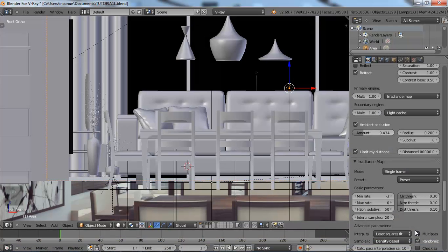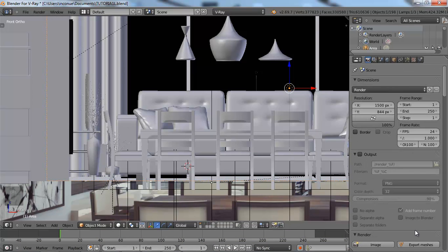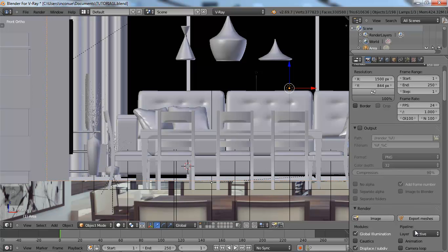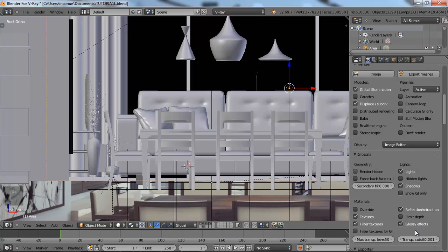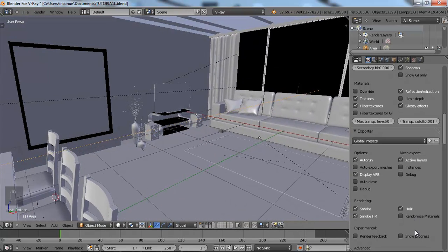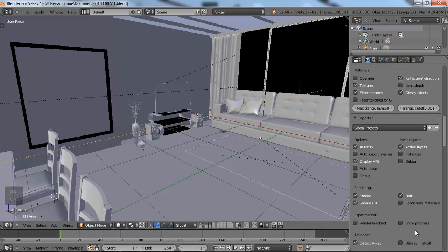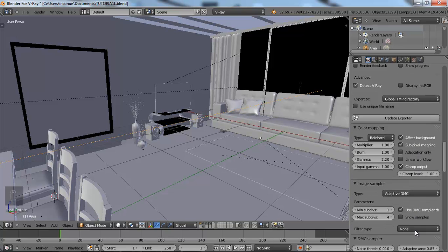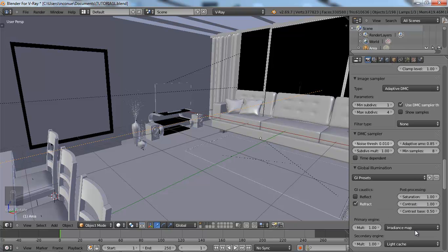but I will talk about the settings used in V-Ray. It's not the maximum setting in V-Ray Blender. First, you have to activate output and add frame. When you finish modeling all the scene and adding all the models, you deactivate auto export meshes. Okay. Now we use 1.4 for image sampler, adaptive DMC, threshold sampler with 0.010, but we can reduce that to 0.05.